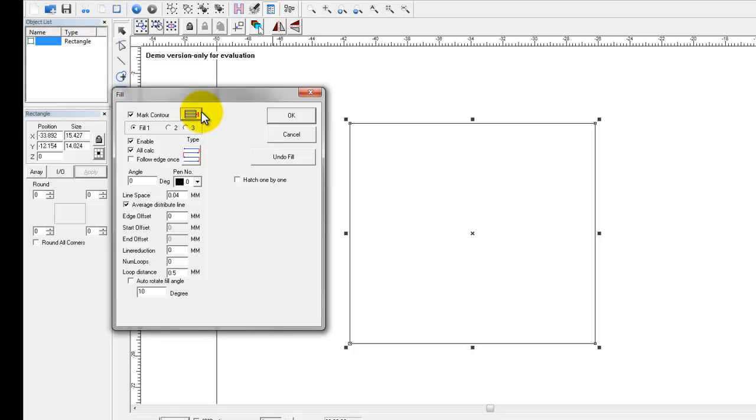The plus sign here next to the 1, if the little dashes, that is a toggle button. If I click that, you're going to see the 1 jump to the outside. What this says is, am I doing the fill first? You can see the inside here, which would represent the fill we're going to place in here, or am I doing the outside first? So which one do I process first in order of operation? If I'm set up in this method here, what we're going to see is that first the fill that we set up will process, which you can see my mouse is inside the square, and then second in the operation, if our mark contour is turned on, it will process this contour. Likewise, if we switch it, it will process the contour or outline first and then process the fill.